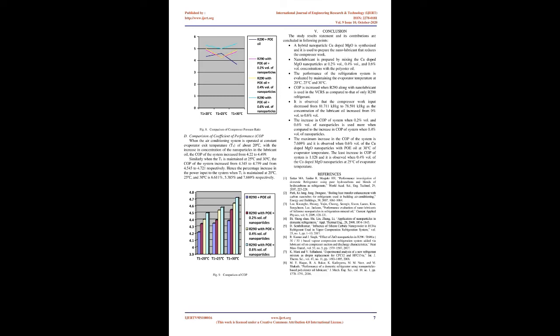V. Conclusion. The study results statement and its contributions are concluded in the following points. A hybrid nanoparticle Cu-doped MgO is synthesized and it is used to prepare the nano-lubricant that reduces the compressor work. Nano-lubricant is prepared by mixing the Cu-doped MgO nanoparticles at 0.2% vol, 0.4% vol, and 0.6% vol concentrations with the polyester oil. The performance of the refrigeration system is evaluated by maintaining the evaporator temperature at 20°C, 25°C, and 30°C.